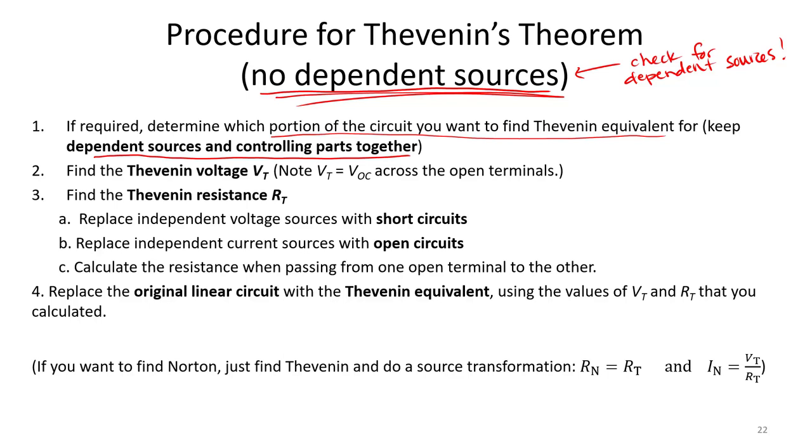Next step, you want to find the Thevenin voltage. It turns out that our Thevenin voltage, Vt, is equal to VOC. Remember the open circuit voltage? The open circuit voltage is the voltage across the two open terminals.